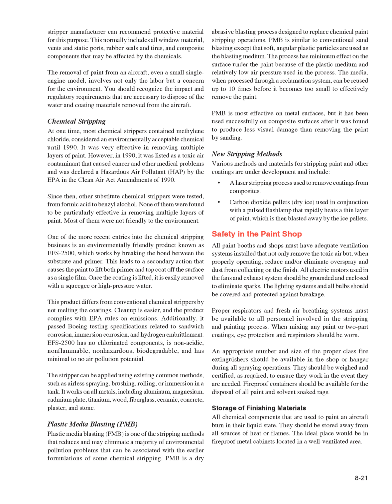Plastic media blasting, PMB, is one of the stripping methods that reduces and may eliminate a majority of environmental pollution problems that can be associated with the earlier formulations of some chemical stripping. PMB is a dry abrasive blasting process designed to replace chemical paint stripping operations. PMB is similar to conventional sand blasting except that soft, angular plastic particles are used as the blasting medium. The process has minimum effect on the surface under the paint because of the plastic medium and relatively low air pressure used in the process.